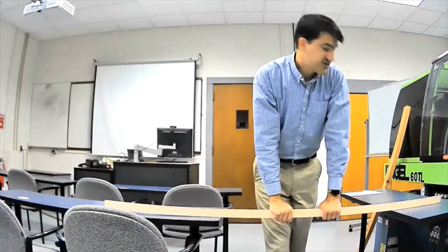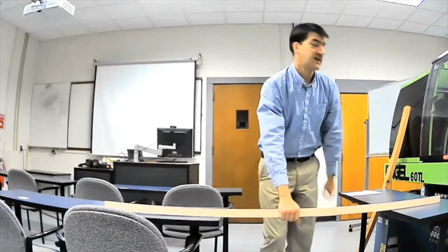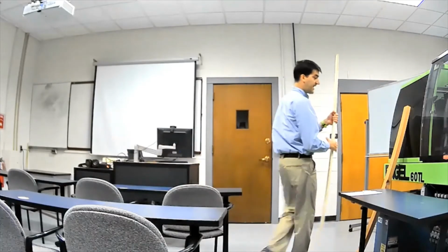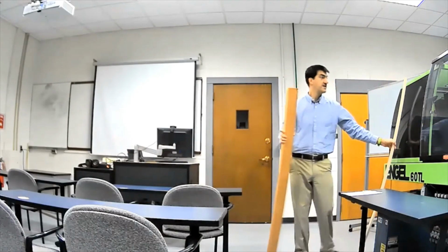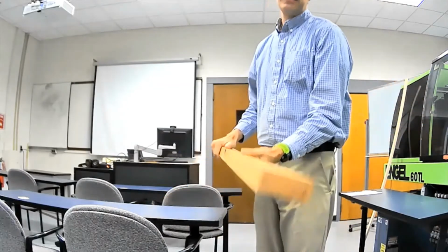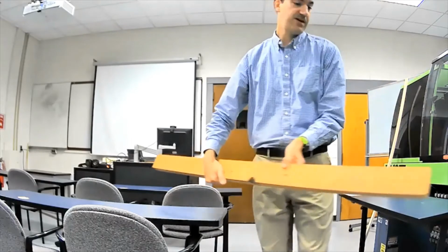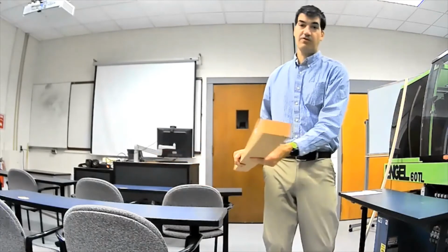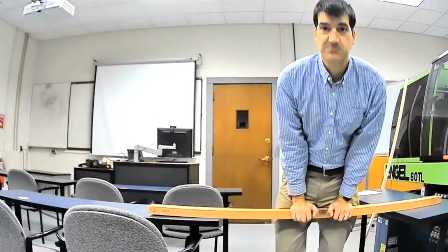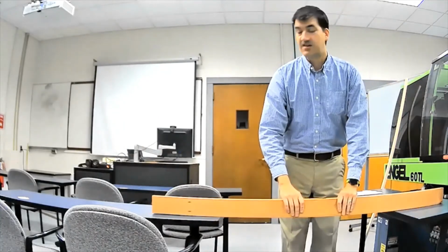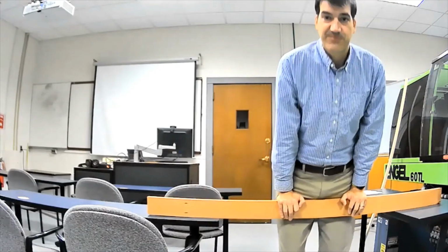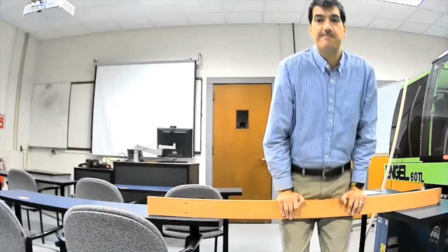All right. As we're talking about dimensions, of course, I could change this out for a larger board, right? So that was a 1x2. Instead of a 1x2, I could use a 2x4. This is a pine 2x4. And of course, I could put it in the horizontal direction like this. And this is pretty strong because it's a 2x4. But I could make it even stronger if I put it up on its narrow edge. Now it barely even deflects when I put all of my body weight on it.